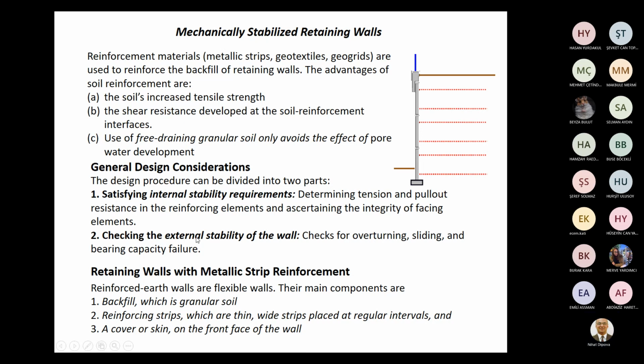Anyway, what does internal stability mean? Determining tension and pull-out resistance in reinforcing elements, and ascertaining the integrity of facing elements. Internal stability means stability of this reinforcement and facing element as well.